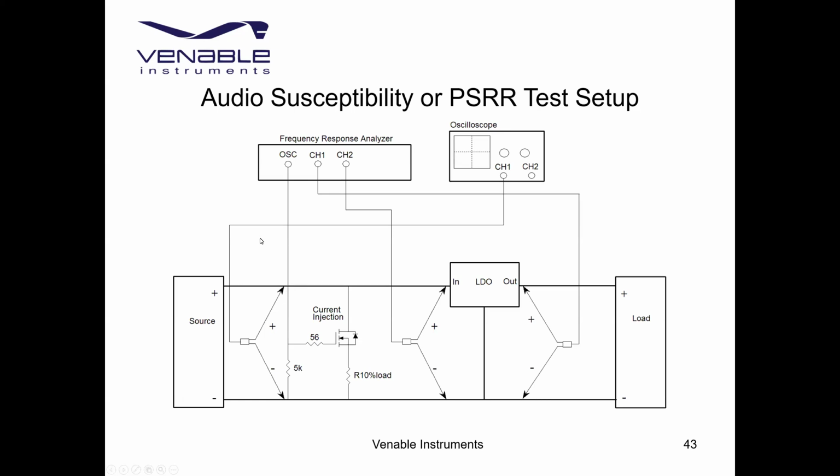So you have to compare your injection level into that resistor at a certain frequency, and then try it on the unit at that frequency, all the way up to 150 kilohertz. They want you to inject a certain power level, but I don't think it makes that much sense, but that's their standard. It's like 80 watts until you reach 5 kilohertz, and then it rolls off to like 90 milliwatts at 150 kilohertz as the minimum. That's a minimum line. You can go above that line when you're doing an injection. That's probably all I know about that. Like I said, I've never done it.